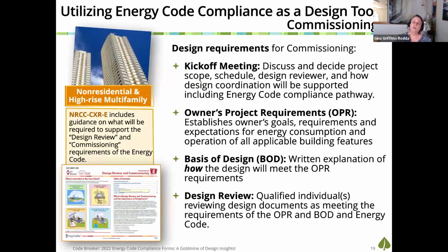In fact, the Energy Code has a commissioning process that's dictated for certain building types to help support this. Why we want to talk about this with you in this particular session is, why not consider the commissioning process even if you don't trigger it? Why not look at flavors of the commissioning process to help support that the owner's requirements and any project goals we have are met? When we trigger commissioning in the Energy Code, it applies to all new non-residential buildings. It is not required for additions, alterations, single family, multifamily, or hotel/motel. So there's a limited scope of when this is required by the Energy Code, but it's such a great process.